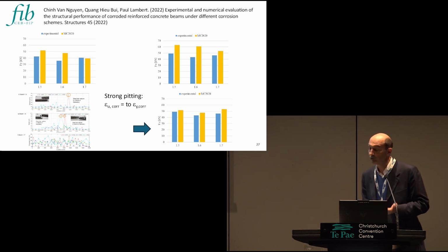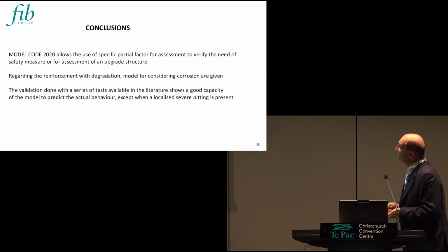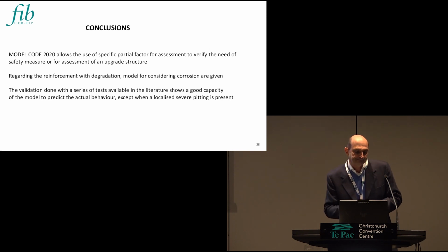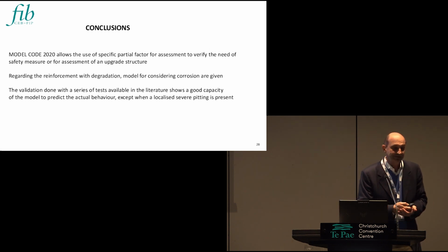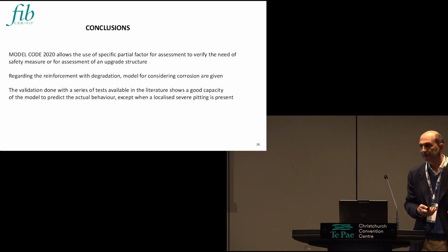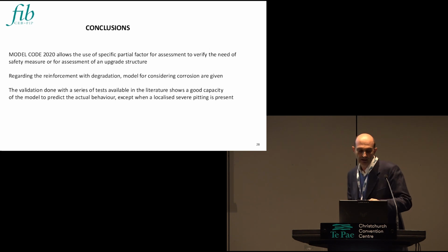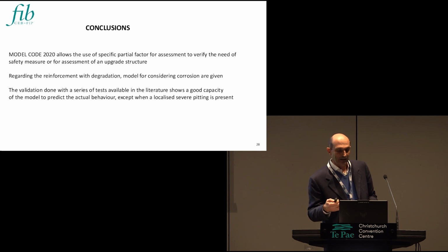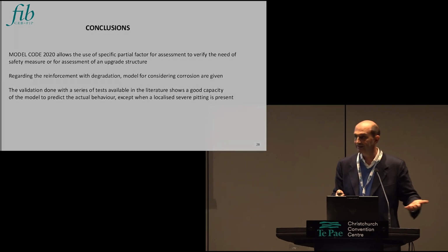So I go to the conclusion. In existing structures we have this new aspect. I think the definition of the partial factor is very important, because for the design, the model of degradation is very important. Before this document, the idea was to consider the degradation only as a reduction of area, not as a problem also of ductility, but if you do also a sectional analysis, we can have very different results. So thank you for your attention.